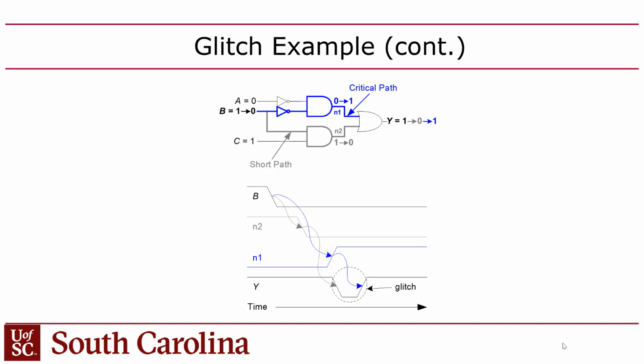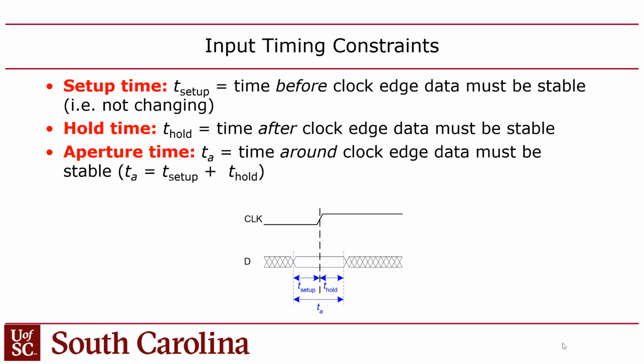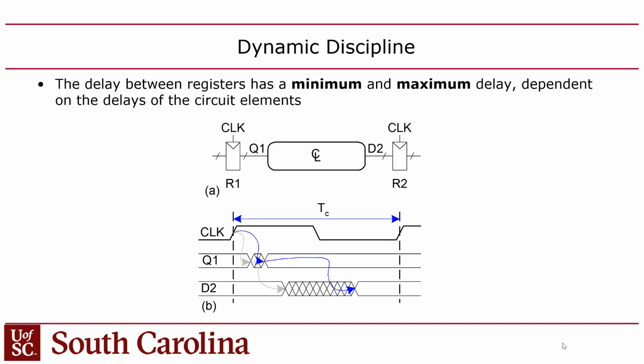I mean, you might figure out where that corresponds to in your Verilog, but you have to keep in mind that your Verilog was translated first to gates, then these paths exist in the gates, right? So it's not always straightforward how to restructure your Verilog in order to fix these. Generally the case is you add pipeline stages. That's generally how you approach the problem. You add registers to break up long paths. But that part is more of an art than a science, because you've got to figure out how to go in and tweak your design.